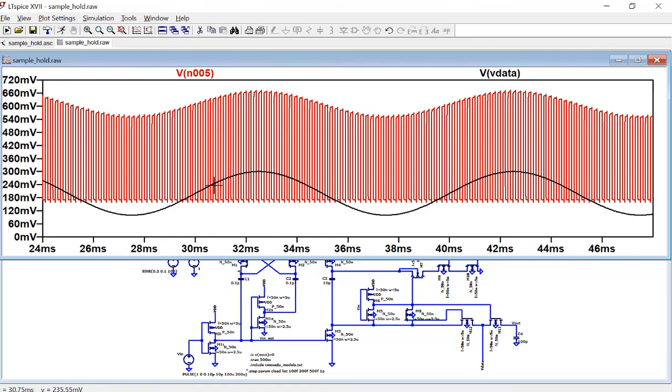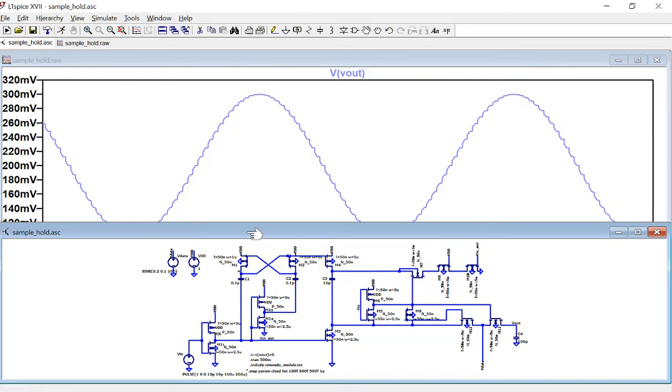You know, the data can be all different kinds of data because it depends on the sensor, right? The sensor is transferring the temperature or humidity or anything to an analog voltage. We use the ADC to sample it. So here is just the signal from the sensor, for example, and it has a DC offset, which is common. You can see the DC offset anywhere on the sensor. And here's the signal. And your VG is tracking that signal to make your VG minus signal, which is VGS, a constant, to minimize the distortion of the sampling. Okay, so that works. If you look at the signal, it's being sampled and held from the data.